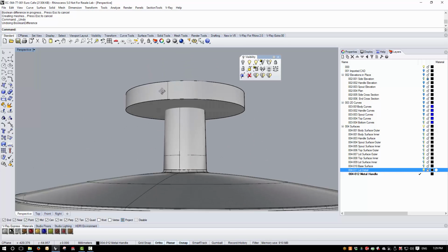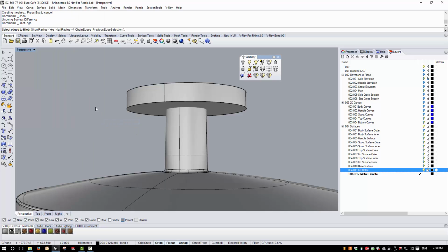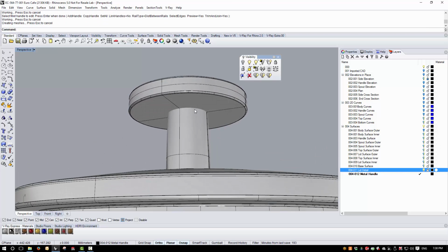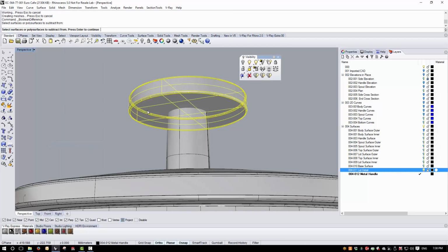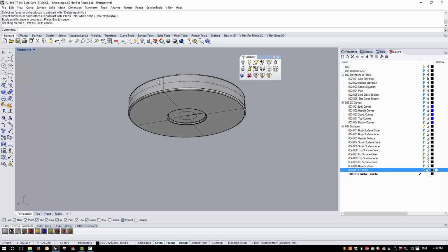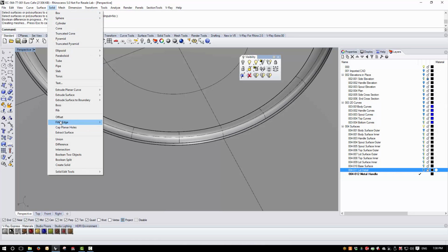So finally we can just put some small fillets on the top and bottom of this, and just to make it look as though this ceramic piece fits into the metalwork here, just going to do a Boolean difference, making sure delete input says no here, and then I can just hide the lid detail, put a very small fillet here.